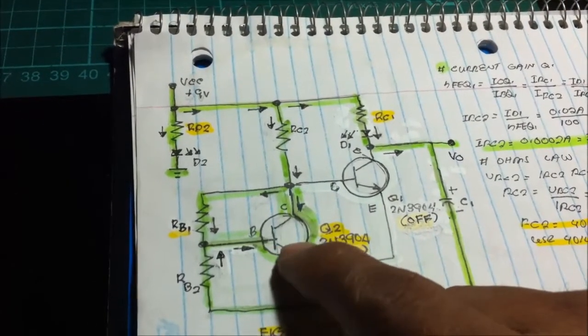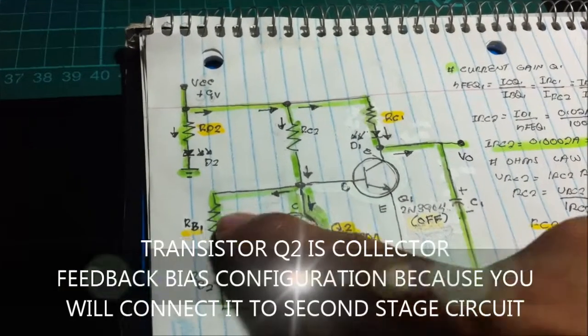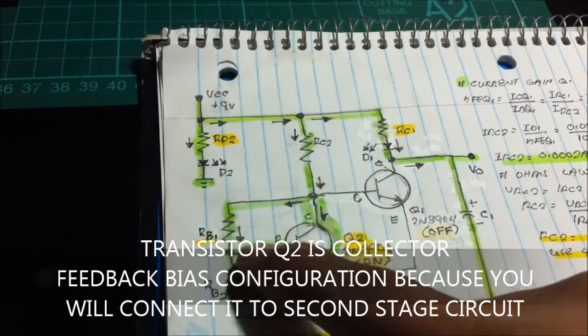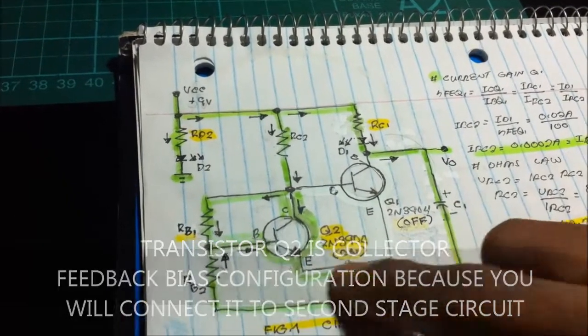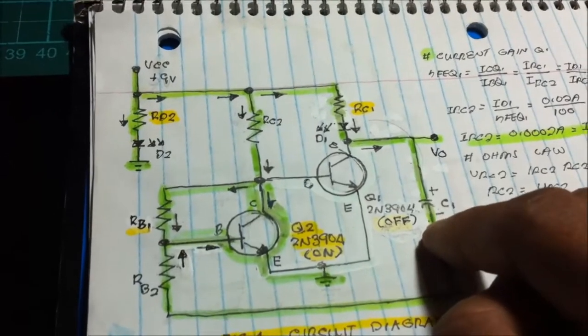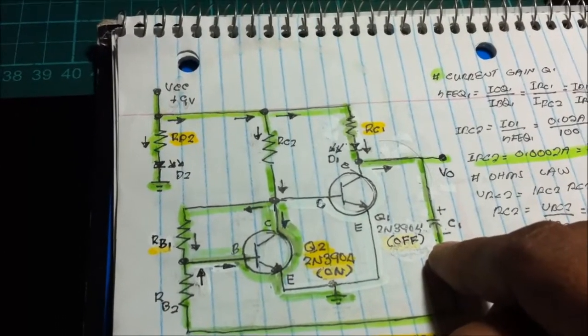What is the circuit configuration of this transistor? Fixed bias. It seems that it is a voltage divider, but it's still a fixed bias. This part is for the controlling component, the capacitor, the charging and discharging action of the capacitor. So let us now analyze the current flow.